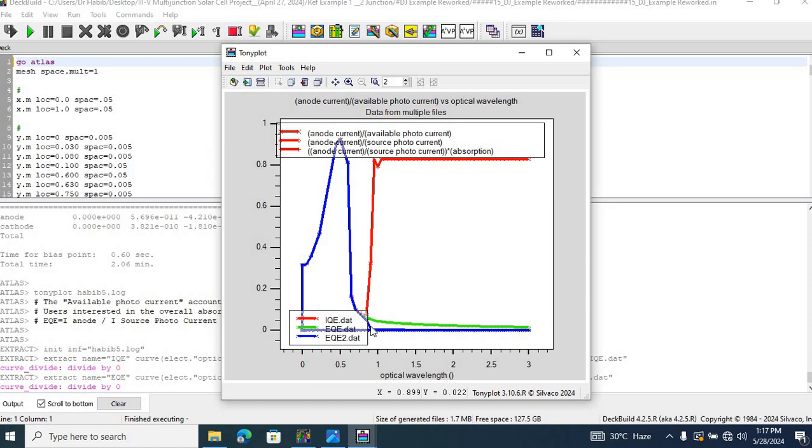We know that the external quantum efficiency is lower as compared to the internal quantum efficiency in solar cells because of several reasons: because of incomplete absorption based on the upper cutoff wavelength criteria and the lower cutoff wavelength criteria, based on recombination mechanisms, for example, Shockley-Read-Hall recombination, Auger recombination, because of reflections from the top surface, etc., and because of so many other different kinds of reasons.